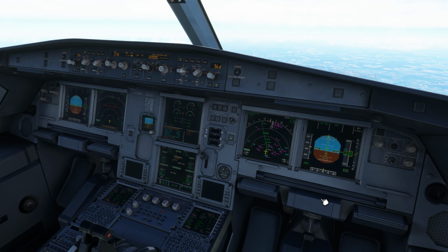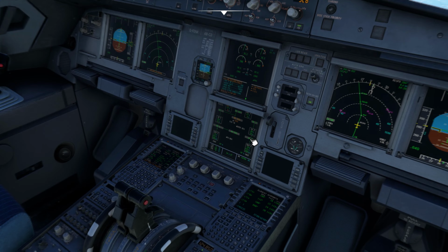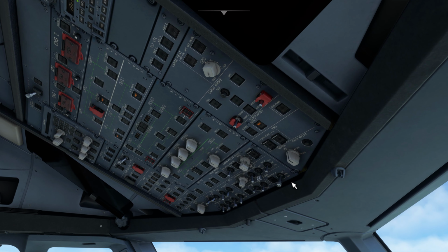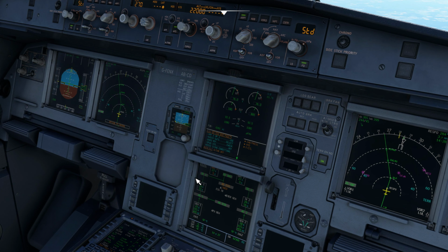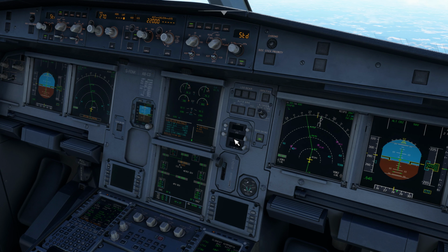Attention, crew at stations. Okay, confirm the failure. ELEC, DC Essential Bus Fault. This is confirmed on the system display page, and also on the overhead panel as well. That's confirmed. I also have offside FM control on my ND, so I can only use the range that you use. ECAM actions.